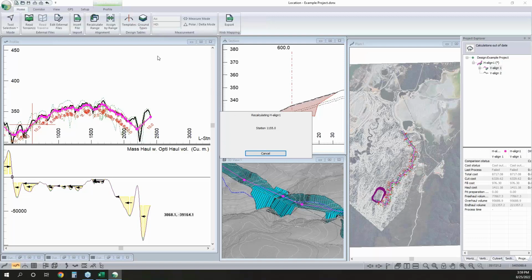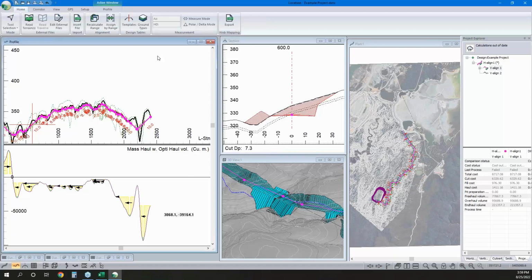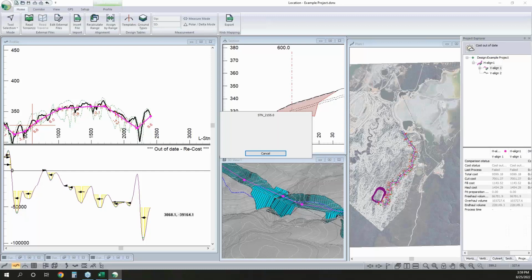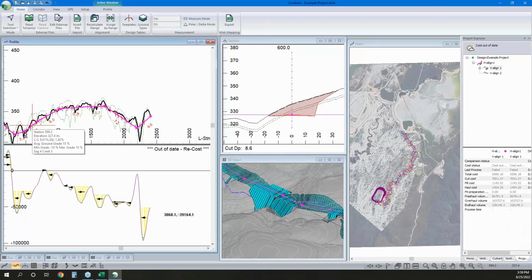So with that, the comment is originally we didn't have the stripping assigned. So if we had our road design and it was balanced, so our cuts and fills equal out without accounting for stripping, and then we actually strip it, basically the material that we can use is lower than what we were planning on, because the first, in this case, 30 centimeters was garbage.